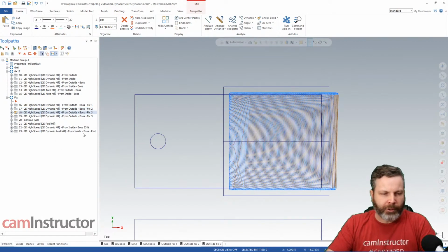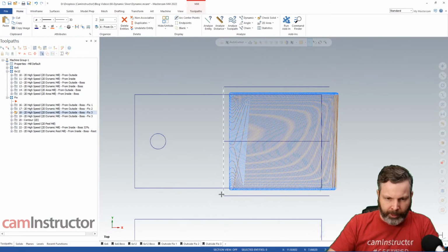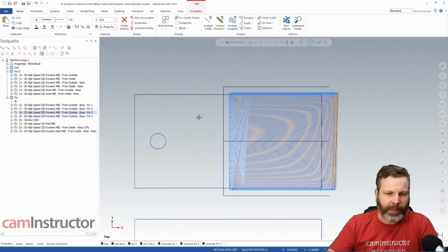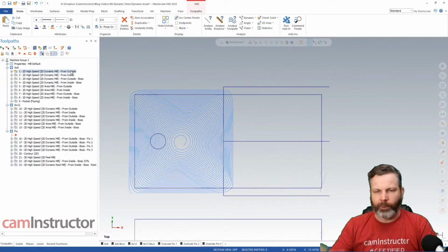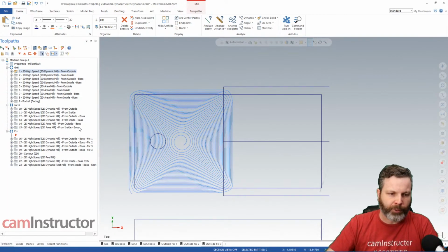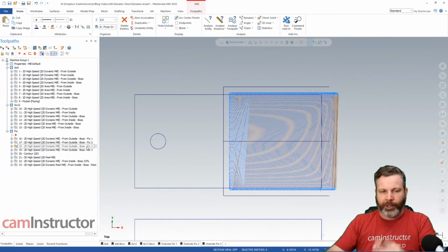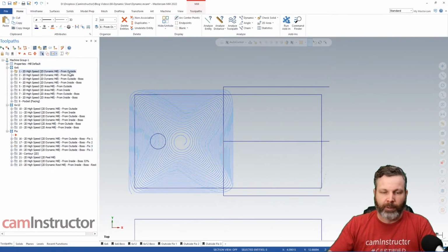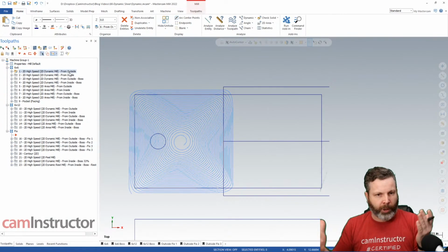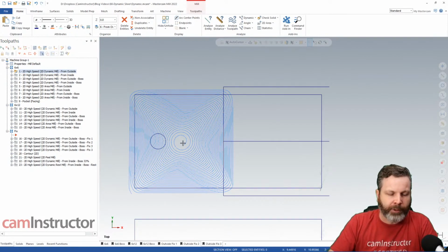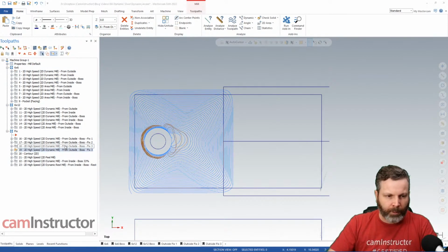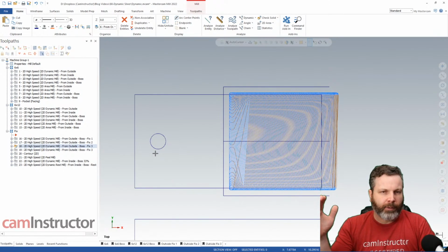So ways we can do that. Here I've got a boundary drawn up right here, and we're machining this part of the part on its own. And then we attack this part over here the same way we did with the 6x6. So we're doing it in two separate toolpaths. One, to get the toolpath more square-ish, and then the second toolpath dealing with it as the square-ish part where we don't get that sliver scenario. So ways that we can eliminate that half.